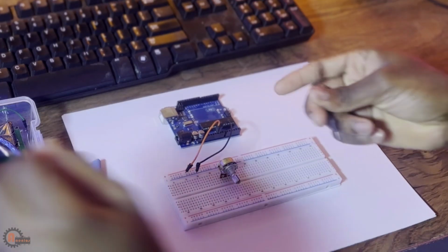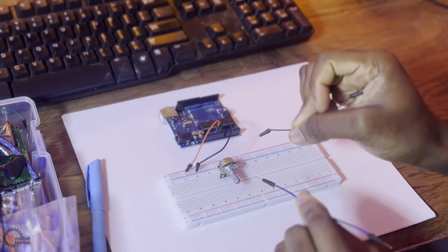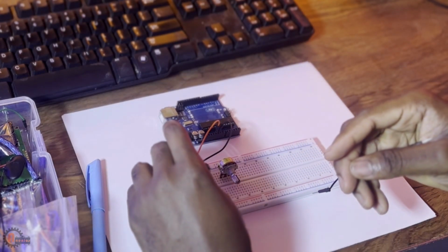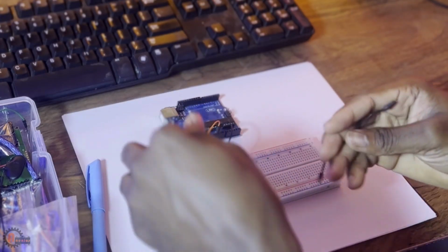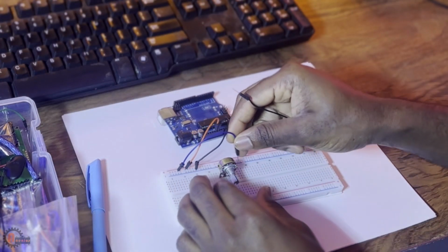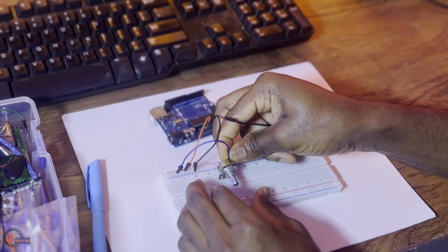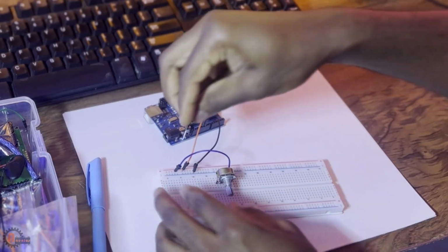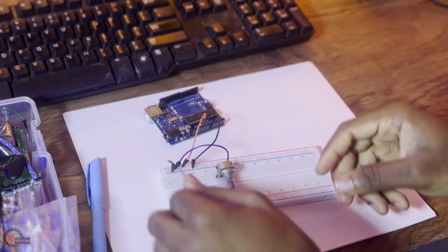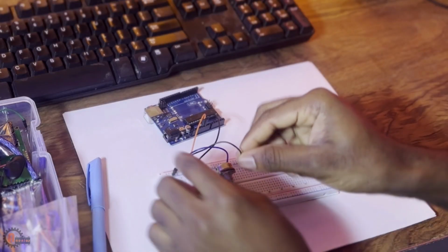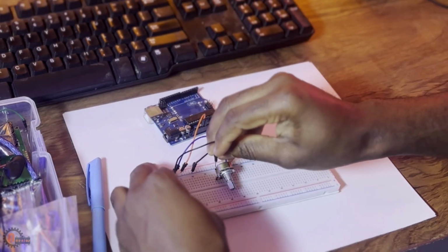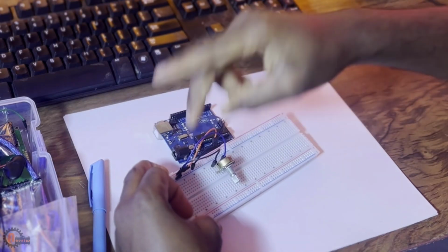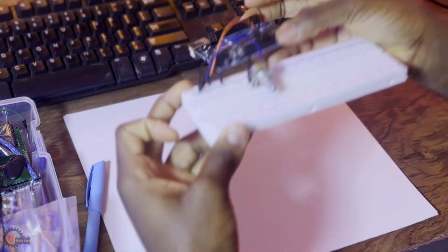So once I now have power from my Arduino board on my breadboard, I can take the same power, which is 5 volts from my breadboard, to the right pin of the potentiometer, and then I take a signal from the ground to the left terminal of the potentiometer. It's exactly what we did on the screen, so I'm just repeating it.